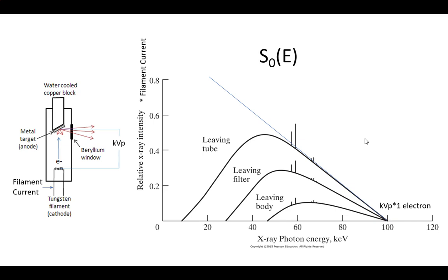Okay, but the main thing, this is the cathode, that's the anode, so there's a voltage difference across here. That's that kVp, the P just means peak, as that's the maximum. Since both sides are equally charged, they go across the same voltage field no matter where you hit on that. So it doesn't matter where you strike, you still went through the entire field strength.